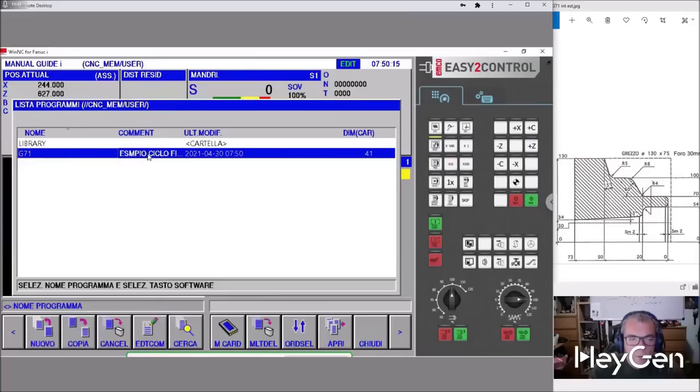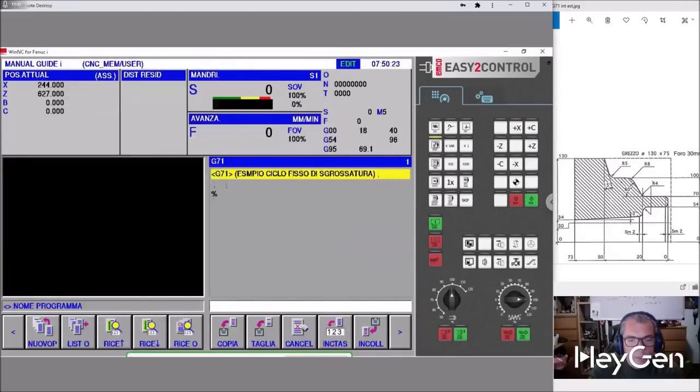Really, folks, for example, a description like fixed roughing cycle might suffice initially. Let's check whether a space is accepted correctly. Not every CNC handles spaces inside comments equally well, some requiring underscores instead. Opening it up reveals an empty little program space, ready and awaiting input.